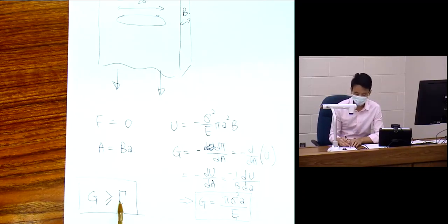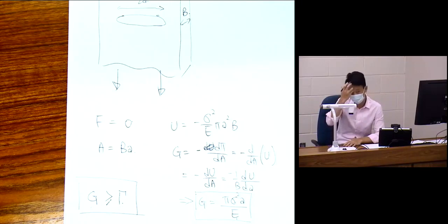Now the fracture energy gamma is not a commonly used term. In textbooks and other literature, you may see more the critical energy release rate. I don't like to use that because it's awfully similar to energy release rate.